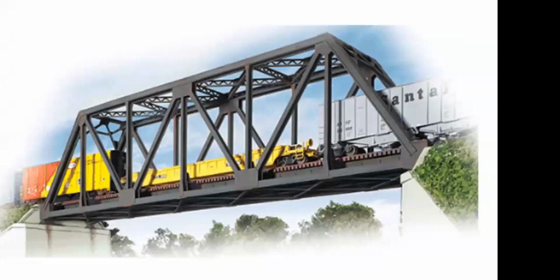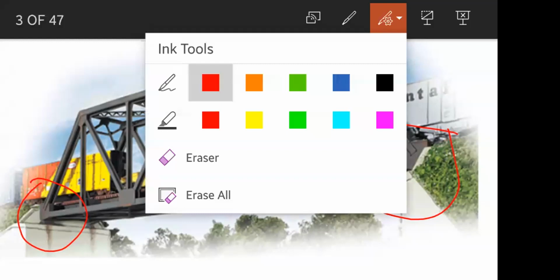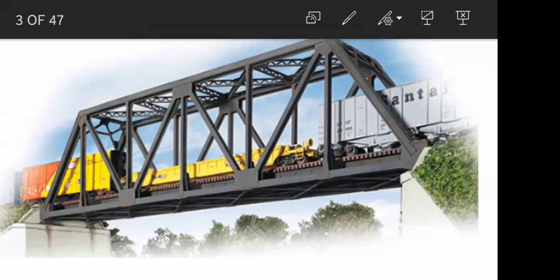For the given diagram, external indeterminacy is completely related to the support reactions. So how can we calculate external indeterminacy for the given truss? First we draw the free body diagram, then we find the support reactions, and there is one equation for external indeterminacy: number of unknowns minus equilibrium equations. External completely depends upon the support reactions. I repeatedly say external means support reactions.